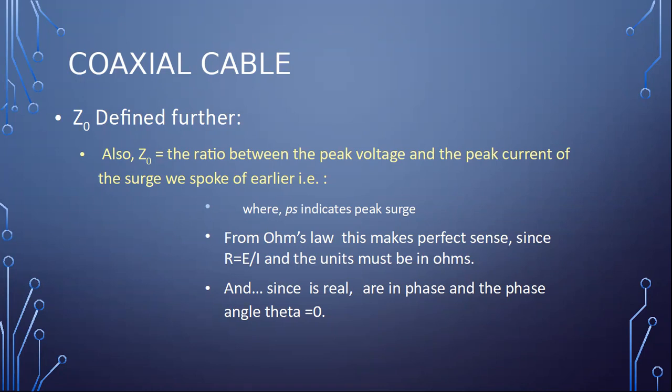Sure, where you're headed. What's the phase relationship in a resistance? There's no phase change. So when that pulse goes down the line, if there is no reflection, if you're looking at something where the whole load is Z0, the voltage and the current are in phase. And so you can easily calculate the real power going down the line with that.